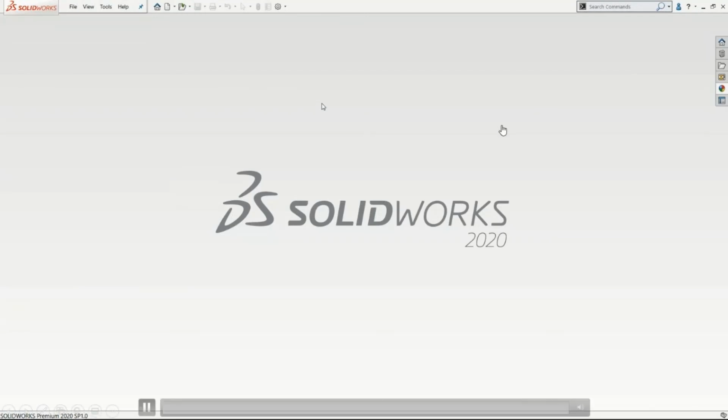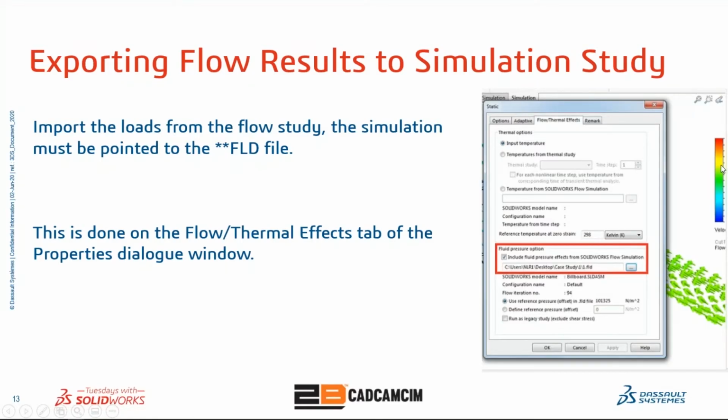We solved the flow simulation study. Then we need to export the flow results to a simulation study. Now we have to import the loads from the flow study. The simulation study must be pointed to the FLD file.